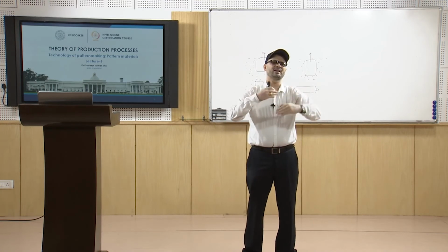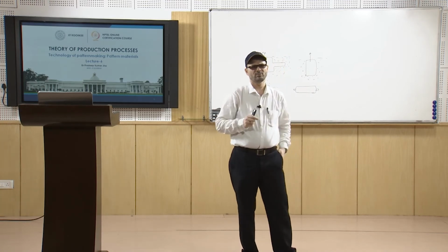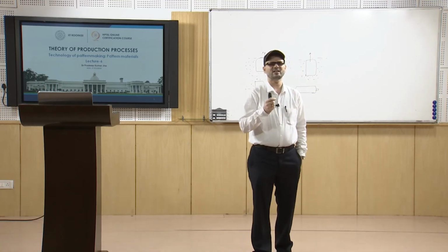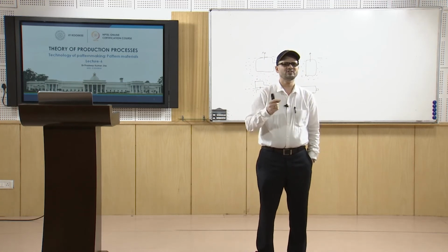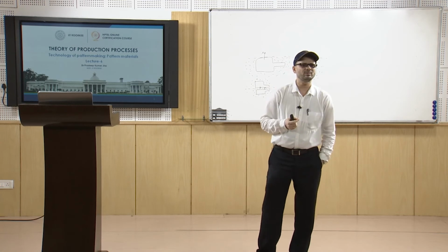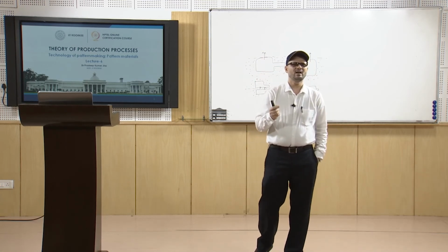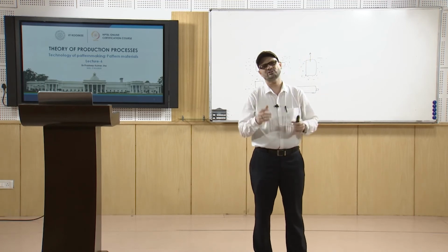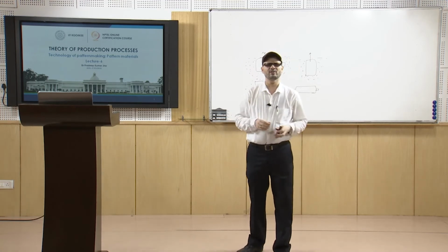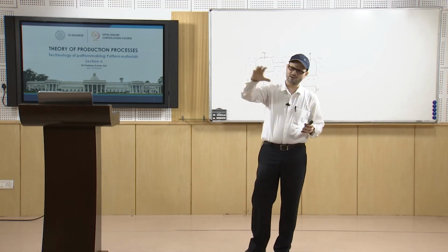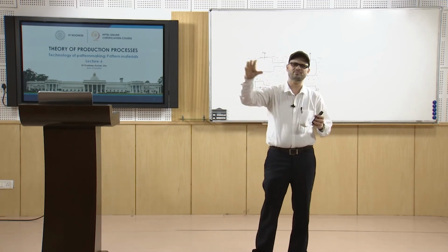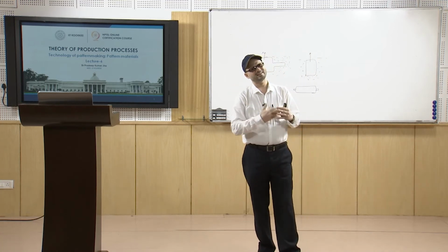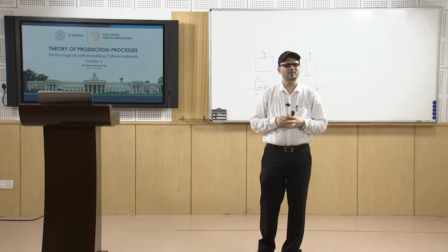So, we do a seasoning treatment to the wood, and during that seasoning treatment, basically it minimizes the effect of subsequent moisture variations by adjusting the water content of wood near to equilibrium level under exposure to average atmospheric conditions. You must have seen many times the wood log is kept in a flowing water river, or it is kept in the atmosphere for 2 or 3 seasons or so, and then it is used. So, basically they are the kind of seasoning methods.